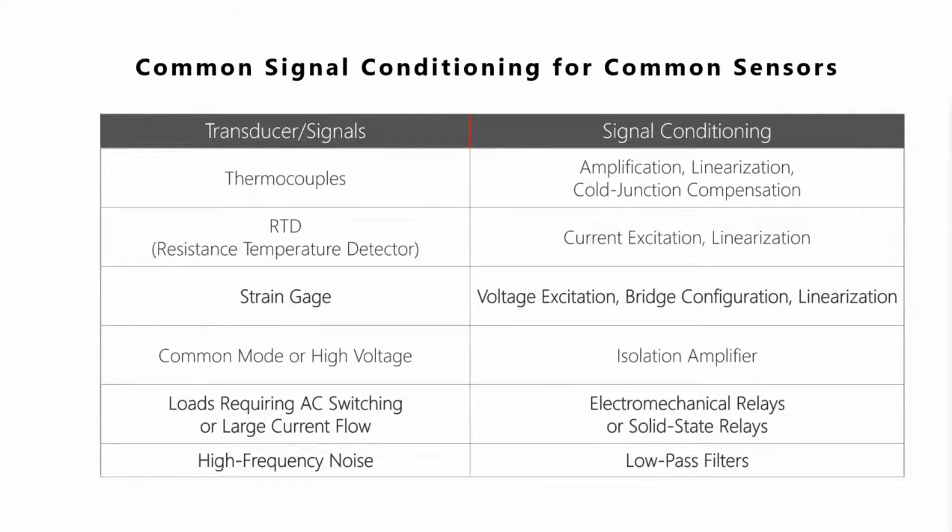Now, beyond filtering that should be done on any voltage signal, some sensors that provide a voltage signal require additional signal conditioning to take a quality measurement. Thermocouples are a great example. To take a strong thermocouple measurement, there are a number of signal conditioning techniques depending on the sensor type. You'll see that later. It depends on the sensor you're using and the signal conditioning it requires. It might need amplification because it's very low, or it might need cold junction compensation.